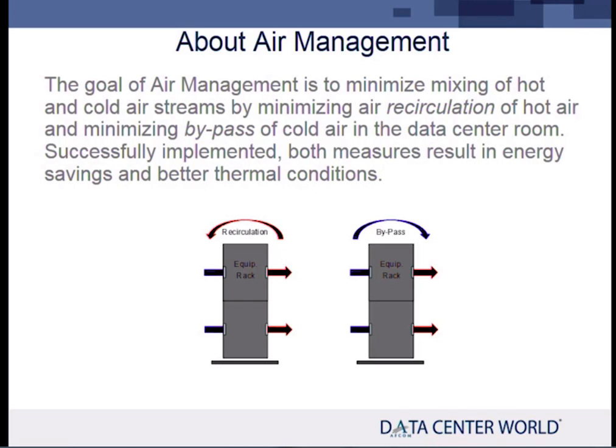Well, what you can do as a rule of thumb is assume about 125 CFM per kilowatt. Okay? Even 100 is a fairly good number. About 125, though, is a better number. That assumes a 25-degree delta T. So take the load in the room that you see in your UPS, right? Go look at your UPS. How much load do I have? Multiply it by 125. That's the amount of air you should be giving the room. That's all it needs. Now, you've got to get it to the right place.